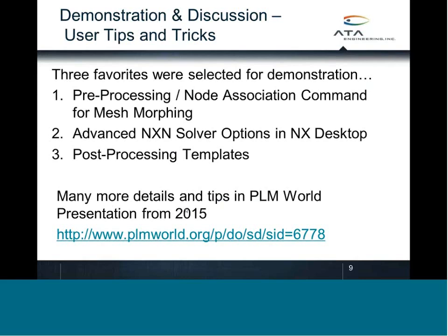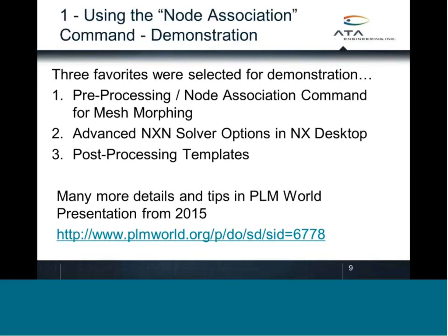So in particular, we'll look at the mesh morphing operation, and in the process, we'll see the node association command. The second tip we'll share with you has to do with the advanced NX Nastran solver options. And the third tip addresses post-processing templates.